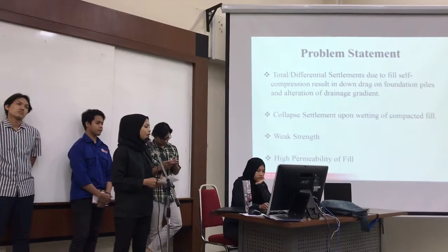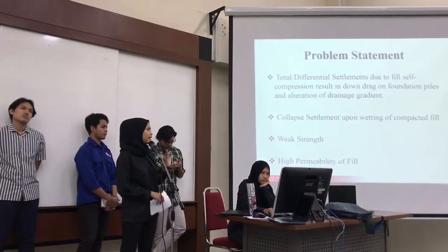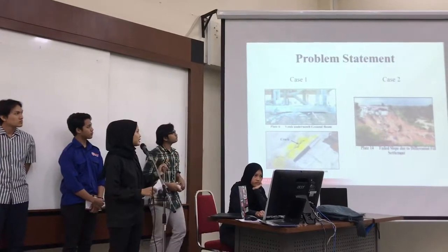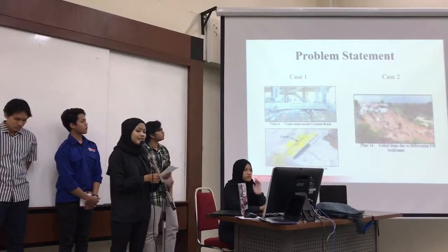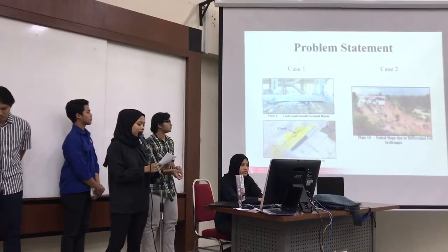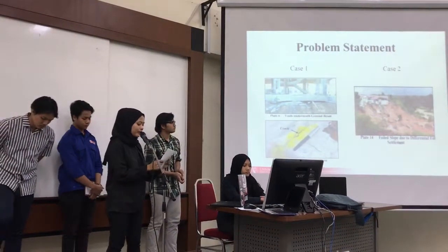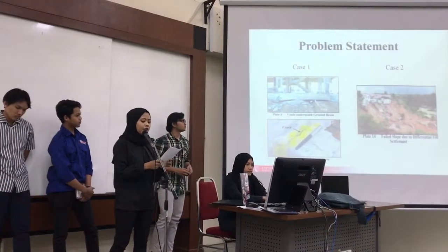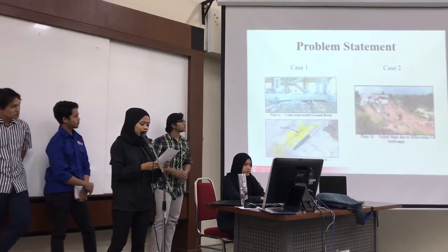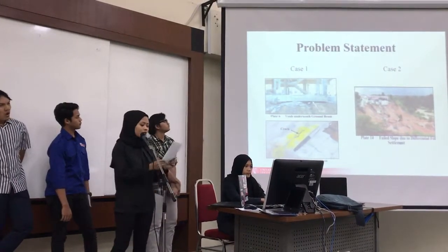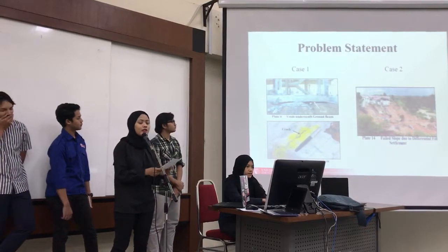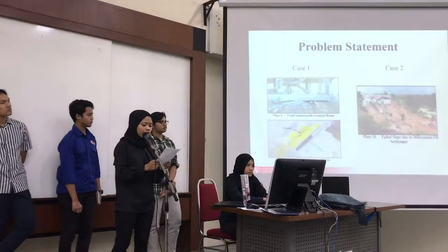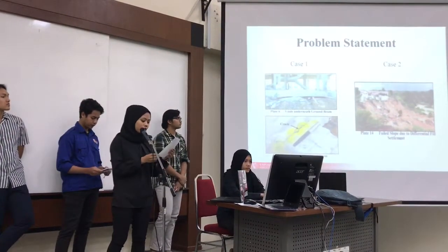Okay, so I will explain the selected cases in more detail. The first case is the excessive foundation settlement and the short piles. It involved platform settlement and structural cracks, where the fill used was cut material which affected the pile installation. It also occurred with an excessive platform settlement, which caused serious structural cracks on the constructed ground beams, stumps, ground floor slab, and structure.